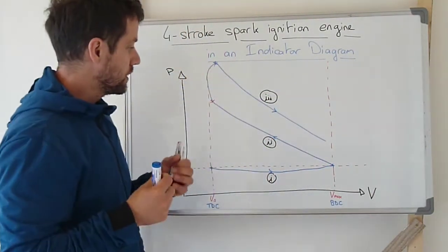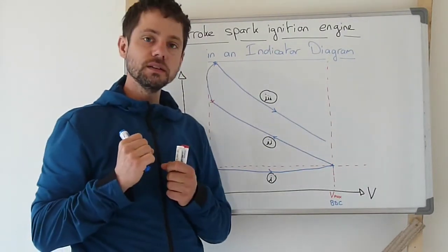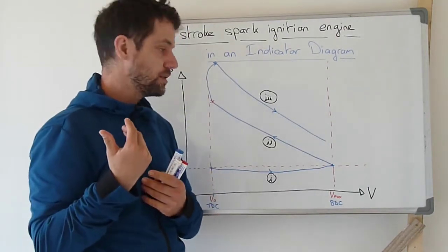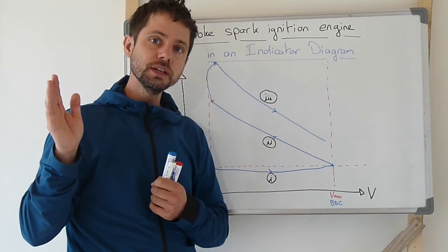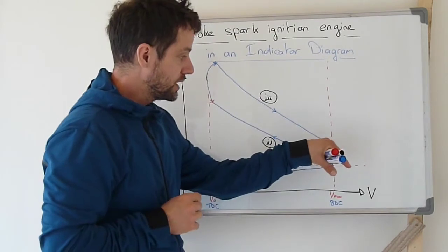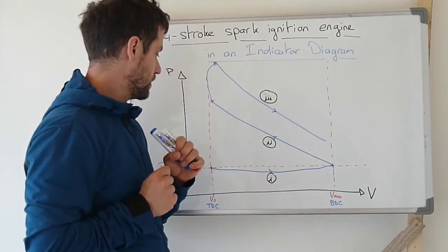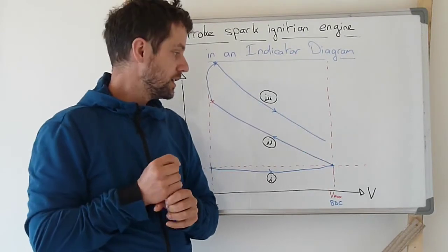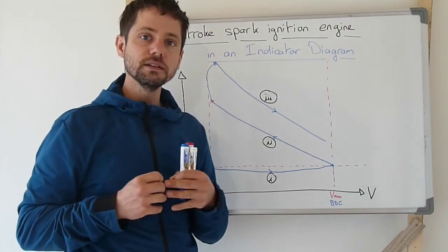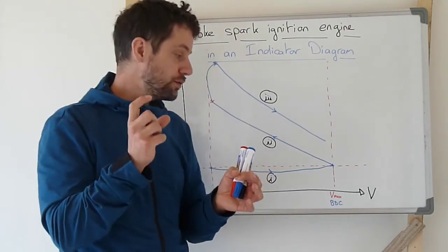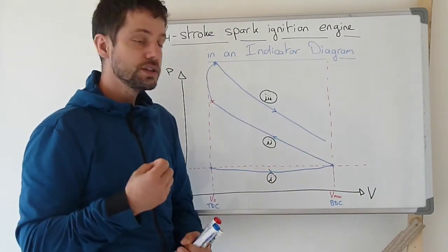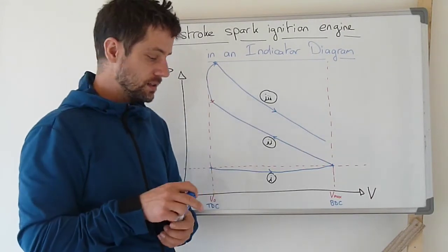And once the piston reaches the bottom dead center, or in fact a little bit before reaching the bottom dead center, most of the time the exhaust valves are opening, and it is connecting the inside of the cylinder, at relatively high pressure, to the atmospheric pressure exhaust line, and this is pushing most of the fluid very fast to the exhaust line, and the pressure difference we get equilibrates with the pressure losses across the exhaust valves.